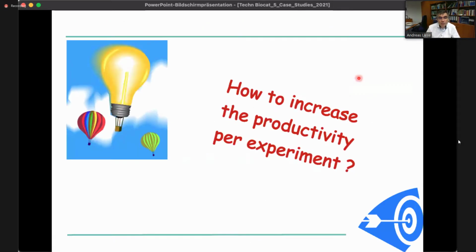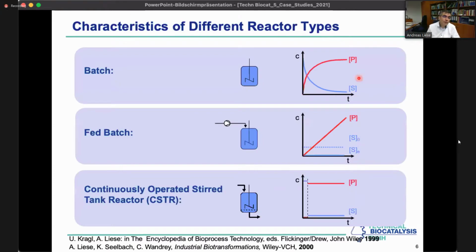Now you see this looks really quite nice, and our target product C is 100% formed with high DE. And now thinking about how to increase productivity, we decided the easiest would be not setting up a continuously operated tank reactor. We just fetch out of our storage a pump and add this to our reactor and then operate a fed batch. And hopefully we can see constant product formation. Okay, so let's do an experiment, and I show you the first experiment we're running.